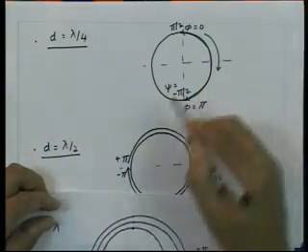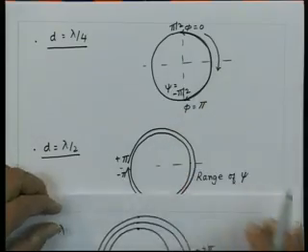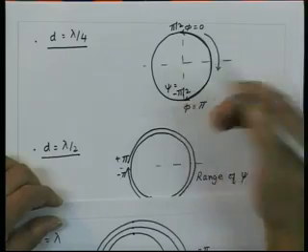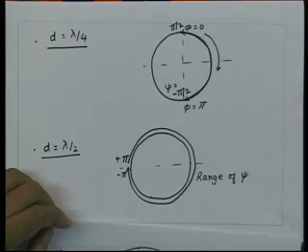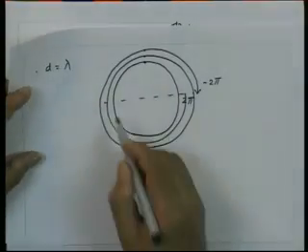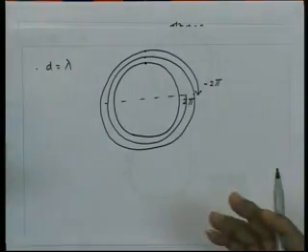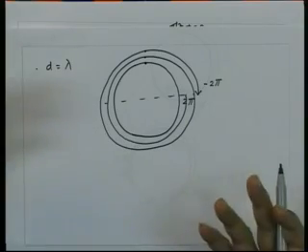So looking at these three cases now, we can make the following conclusions. In this case, since the entire range of angle psi from 0 to 2 pi is not covered by the visible range of psi, there are certain nulls which can be there in the polynomial which may not be physically visible. If I go to this, when the range of psi overlaps with itself, then we do not have independent control of every point on the radiation pattern.